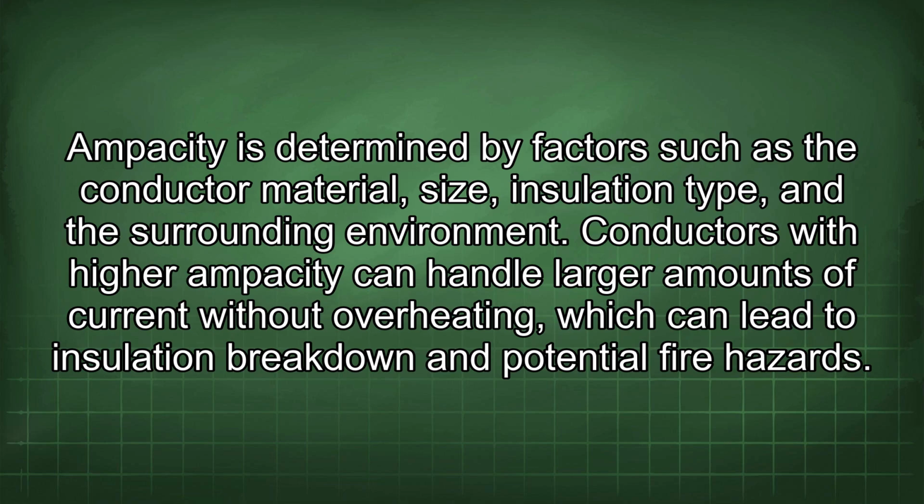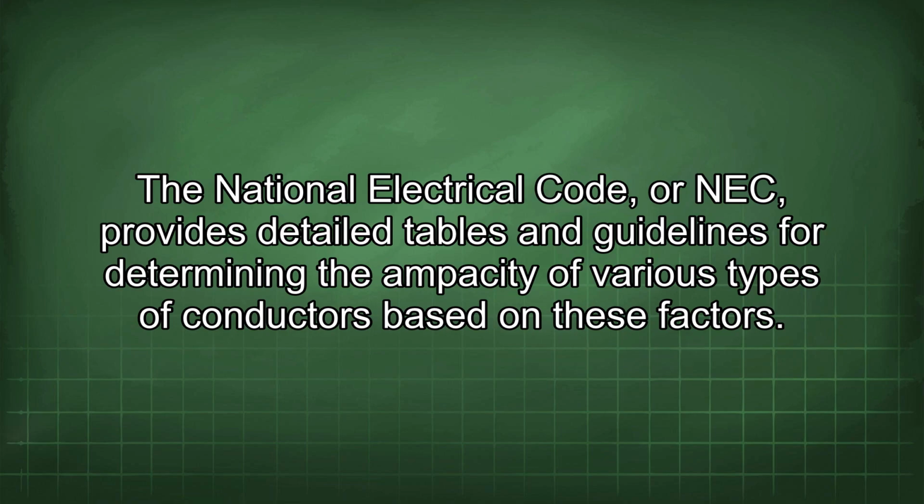Conductors with higher ampacity can handle larger amounts of current without overheating, which can lead to insulation breakdown and potential fire hazards. The National Electrical Code, or NEC, provides detailed tables and guidelines for determining the ampacity of various types of conductors based on these factors.